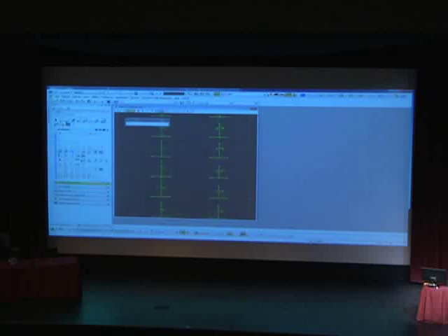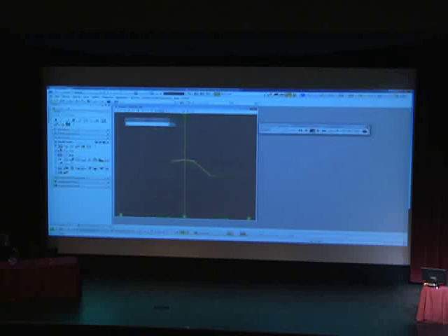I'm bringing up my classic tools here. I have all mode tools. I'm going to bring up the cross section navigator, and then you can easily just flip through all the cross sections. So I thought that was really good. It's still a really good benefit, because I still personally like to use a lot of those old tools when just checking to make sure everything's tying in correctly.